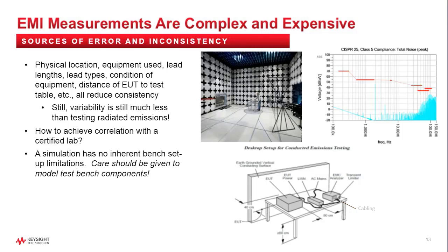But the things that are an issue here are from one chamber to another, you need to make sure you have some consistencies in the setup. So the equipment used, the location, the configuration, and these are all part of certifying the lab. And point being that at some point you will have to go into the chamber and make your measurements to get your type certification, but why not do this as much as you can in the simulation environment before you get there, just to have a good, confident feeling that you have a deterministic analysis done and you're confident that your EMI standards are going to be met.